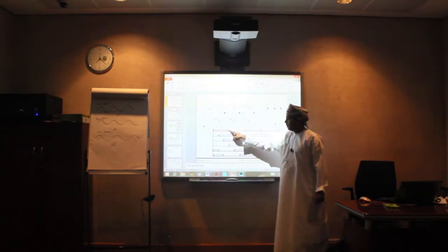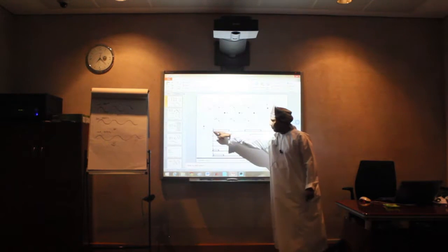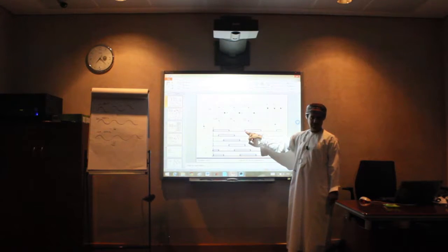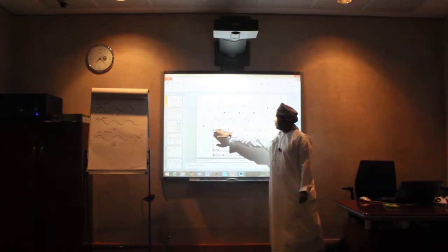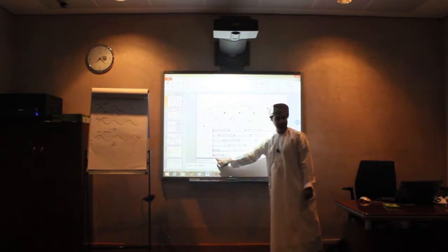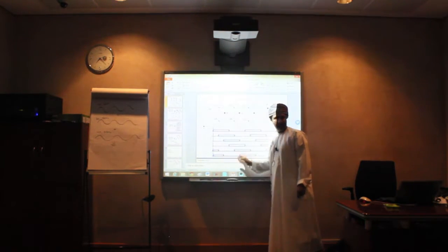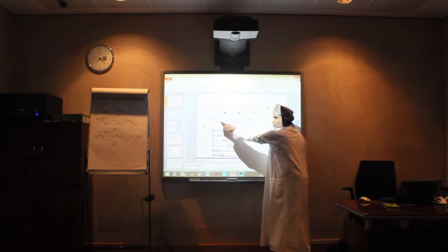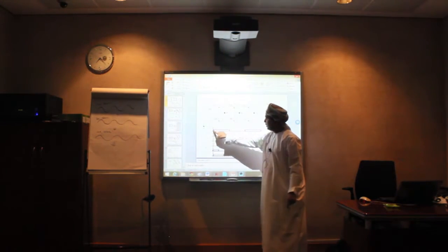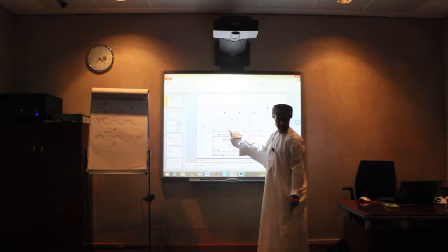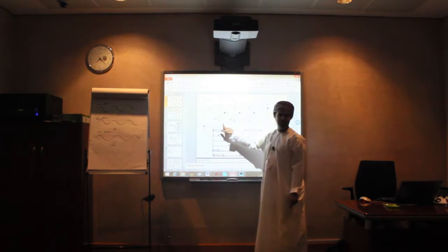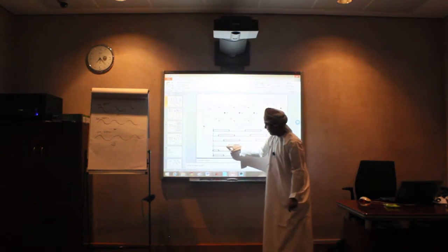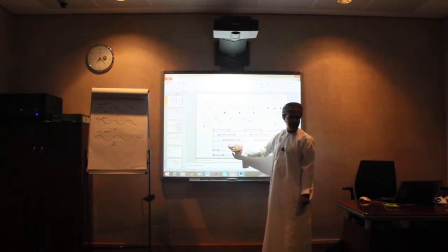So the first switch will be on for 120 and then off for 120. Okay? And now this one, we have seen it like this one, right? In those intervals. Now if we look at that one, the opposite of this one, 4, right? If this one is on from 0 to 180, this one should be off from 0 to 180, which is Q4. See? The opposite.